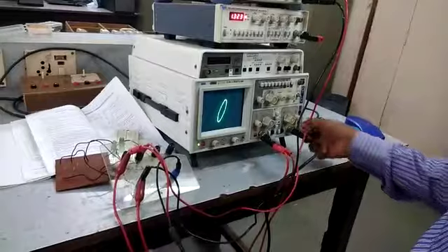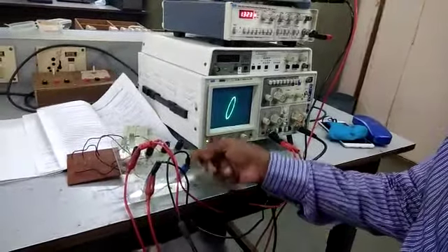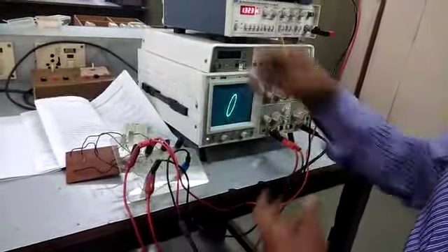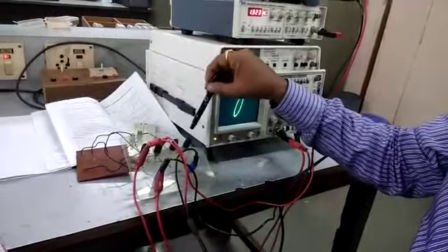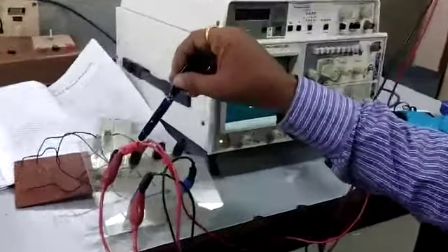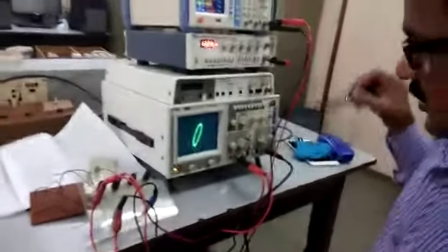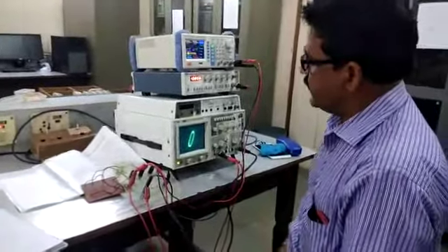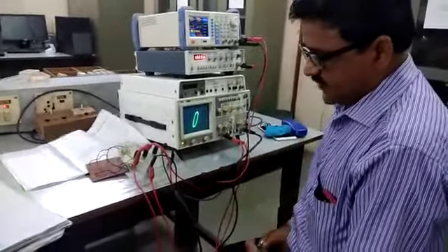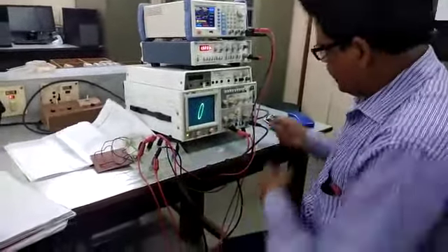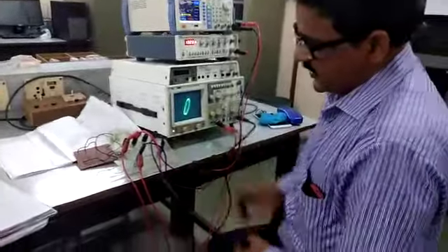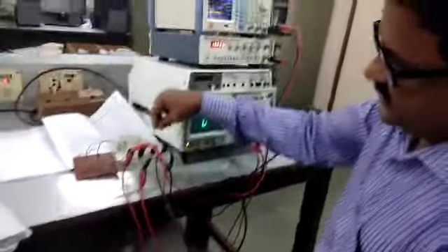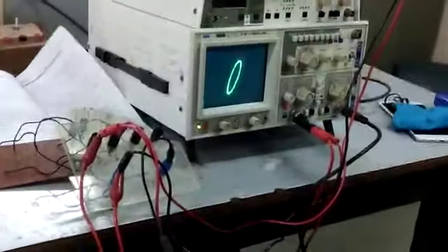Now one terminal of channel 2, common, is connected to common, and you can change the phase shift like this, 30 degree, 60 degree and 90 degree. Now my phase shift here is 30 degree. These are the connections. And what is the procedure for this? The procedure is, you can see here 1 kilohertz frequency at any particular value of amplitude. Then it is given to the RC network, connections positive, negative. From the second channel, common is connected to common, and you can change the phase shift like this. Now it depends on the circuit.